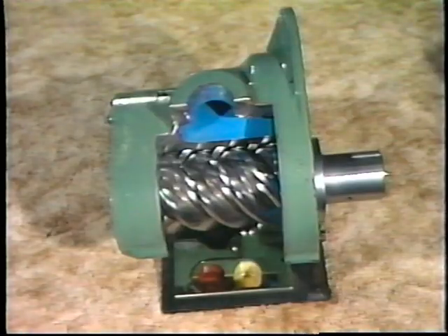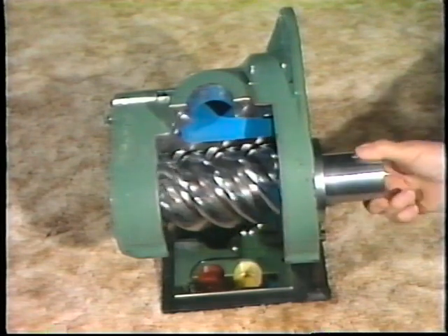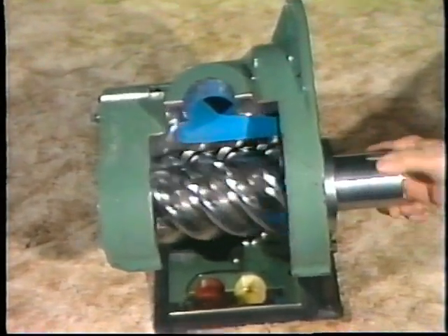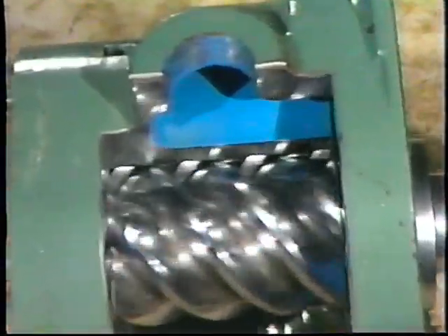Oil-flooded compressors, like the one we've already looked at, are available in a range from 7 to 1,000 horsepower. Because the oil gives you a better seal between the helixes and acts as a coolant, the oil-flooded compressor can be operated at lower speeds and higher pressures in single stage than the dry type. There is one characteristic to keep in mind, though. An oil separator is required to remove the oil from the air.